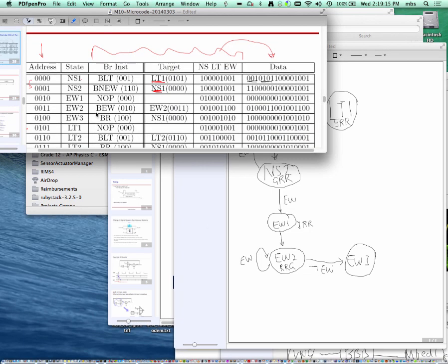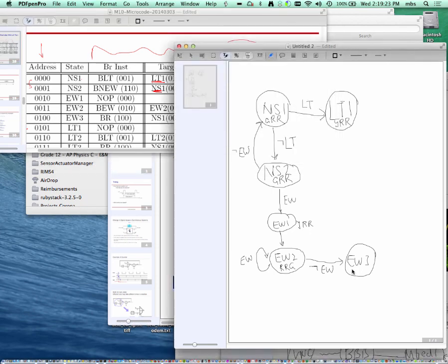And looking back out here, east-west 3, the output is red, red, yellow. So now what has happened is the east-west sensor says there are no more cars. So we are coming out of that one. We are turning the light yellow in east-west direction, and then we will go back to north-south green.